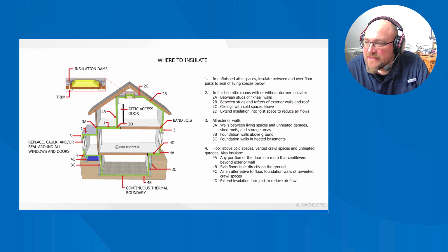It is recommended that the insulation installed in the attic covers the top of the attic floor joists. It is also recommended that insulation sheathing be installed on stud walls. Wood studs can transfer energy through the wall assembly. Metal studs can transfer energy much better than wood studs can. As a result, metal walls' overall R value can be as low as half of the insulation's R value.